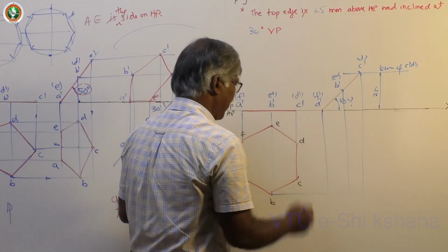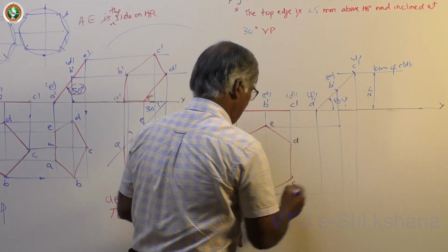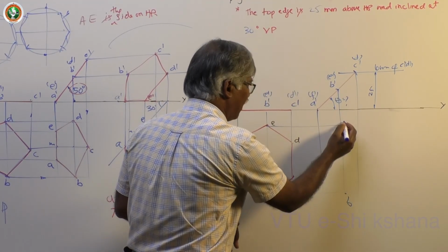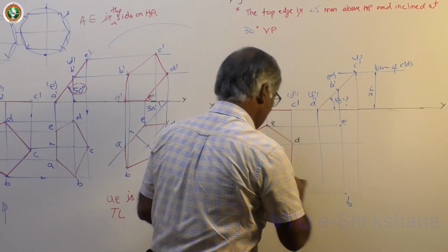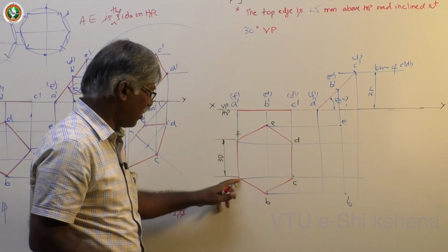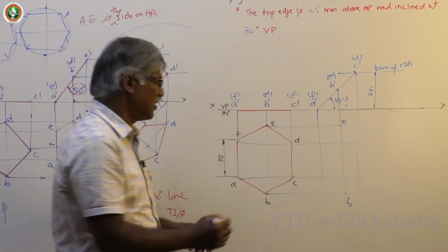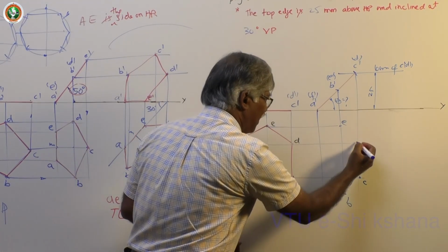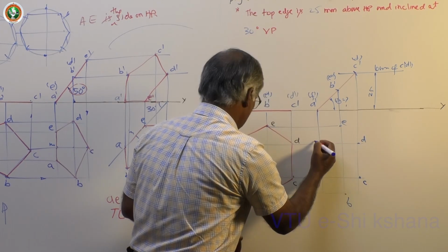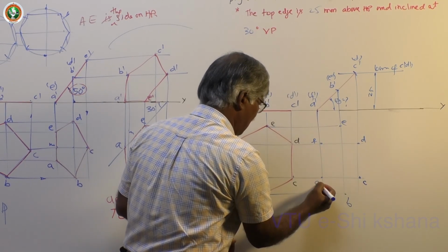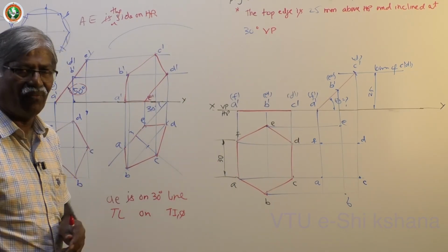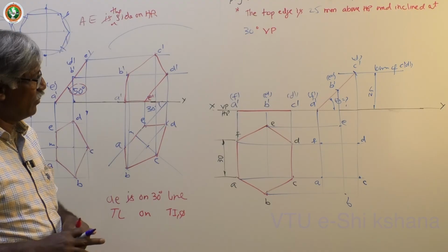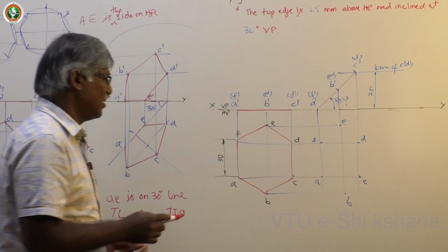Even draw a thin line. Then E will stop here. Again, B is already available here. This is E. Then if you draw two lines, that fetches 4 points for you. See, I have drawn two lines only, and you get 4 points ready. This is C, this is D, this is F, this one is A. So you can optimize your method of working by drawing the minimum number of lines and getting the points. You should not go on searching for points, it's easy.